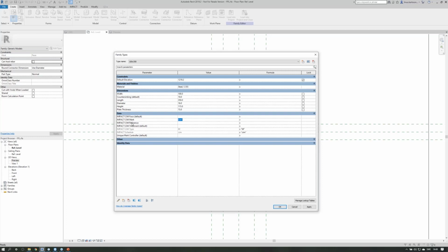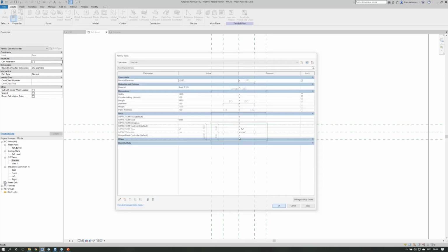So it's basically the name of the custom material, and it needs to be unique, because that's how we separate and pick specific custom materials in different parts of the modeling. So here I want to change this. I will take 98, because I don't think we have used that number yet. So we hit apply and OK.